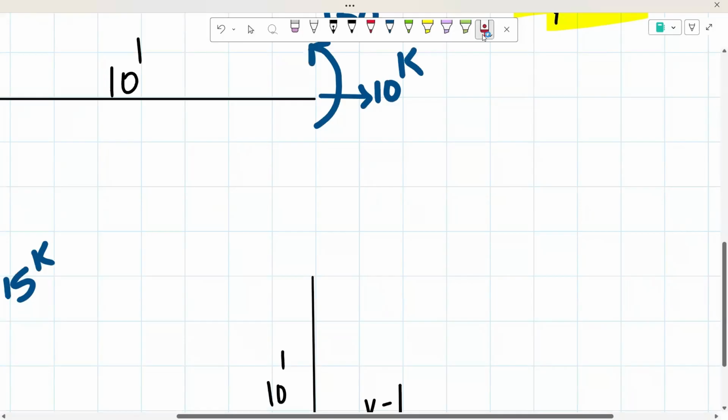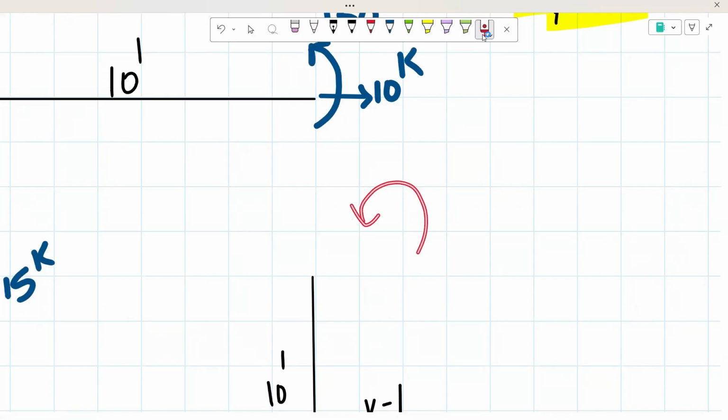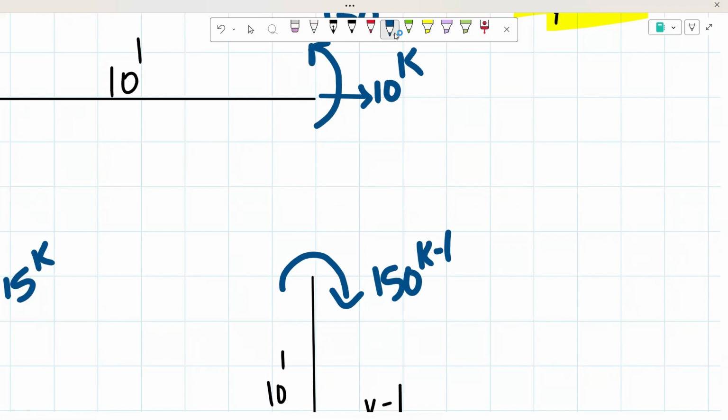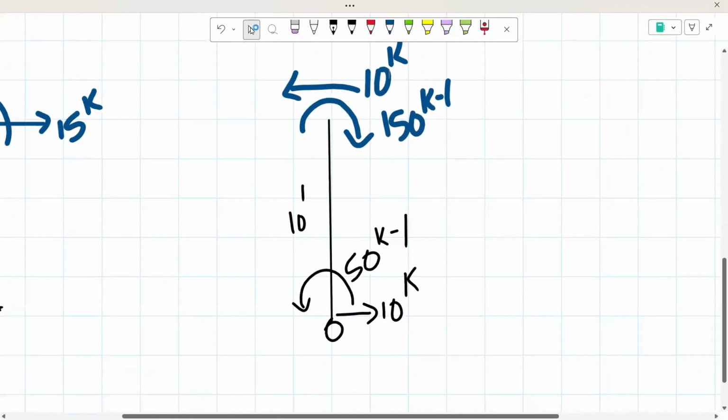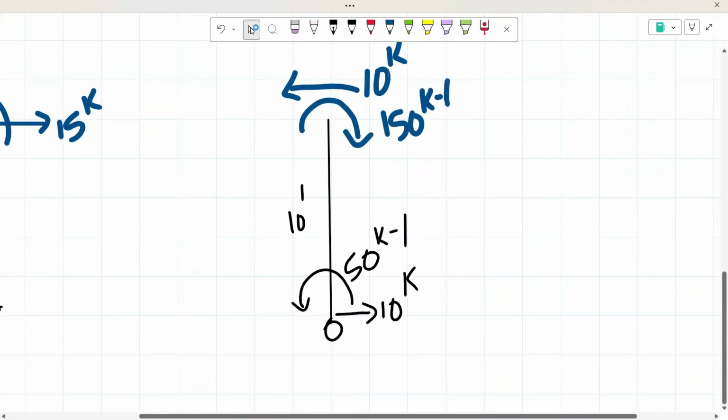As you could see, on this side of the beam we ended up adding the 150 kip feet going counterclockwise. So that means that on this side, we're going to need 150 kip feet going clockwise. And since we have 10 kips acting to the right on this part, we're going to need 10 kips going the other way on this side. So we have 10 kips. Now that we added everything, we could proceed and look at this example.